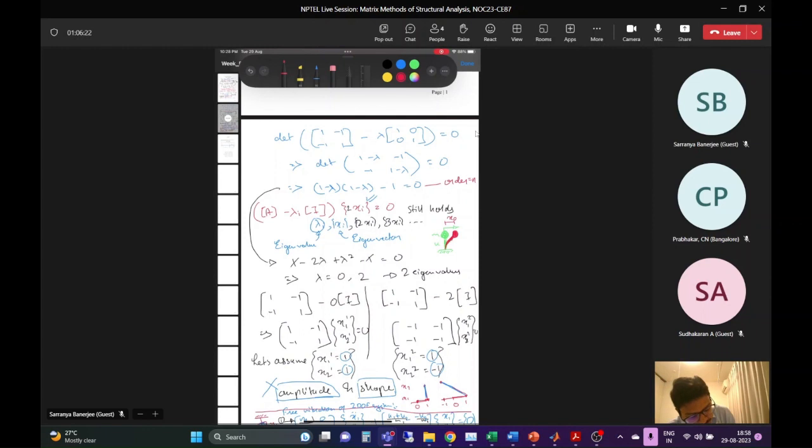If we displace the system a little bit, it will vibrate on its own. It will not vibrate on its own if we do nothing, but we have to do something. You can give it some acceleration: you take a hammer, hit it once. Or you can give it some displacement: hold it, displace it to some position, leave it, then it will vibrate on its own. Or you can give it some velocity: hold it, move it fast and leave it, then it will vibrate freely.